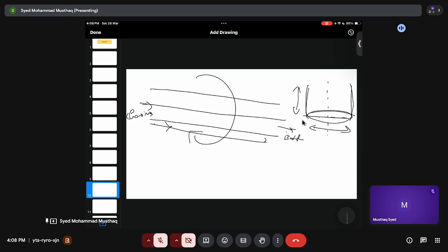And the fluidized bed process we have already explained. There are again vertical low shaft furnaces. There are different things. Now coming to the sponge iron making. So what are the different things that we find? If I talk about the rotary kiln, the horizontal one, you feed iron ore, you feed coal, not coke, please remember, and you feed flux.